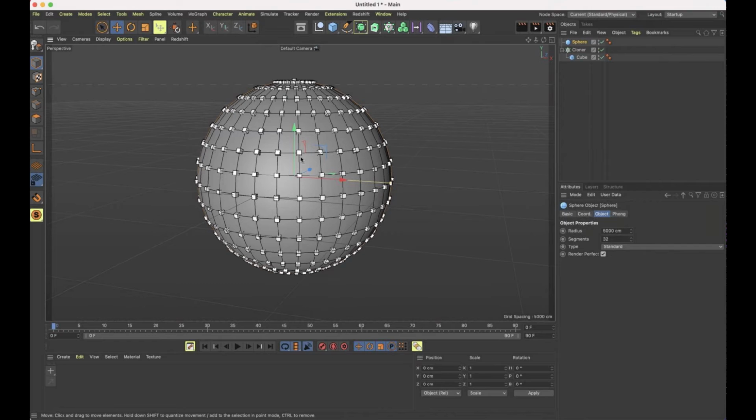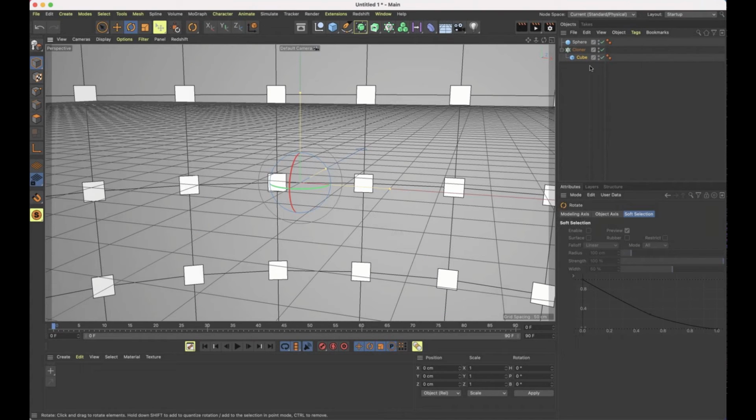After scaling or moving an object, how do you get the little dots back to modify it? Could you just show how to get them, the orange handles? Yep. So you need to make sure you are on the cube, and then you are on object mode, and then you are on one of the move, scale, or rotate tools, and that will give you the orange handles.